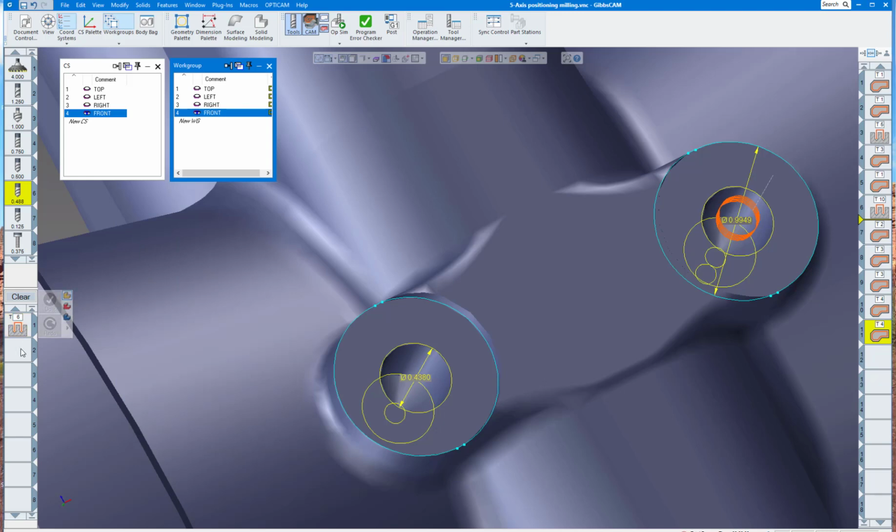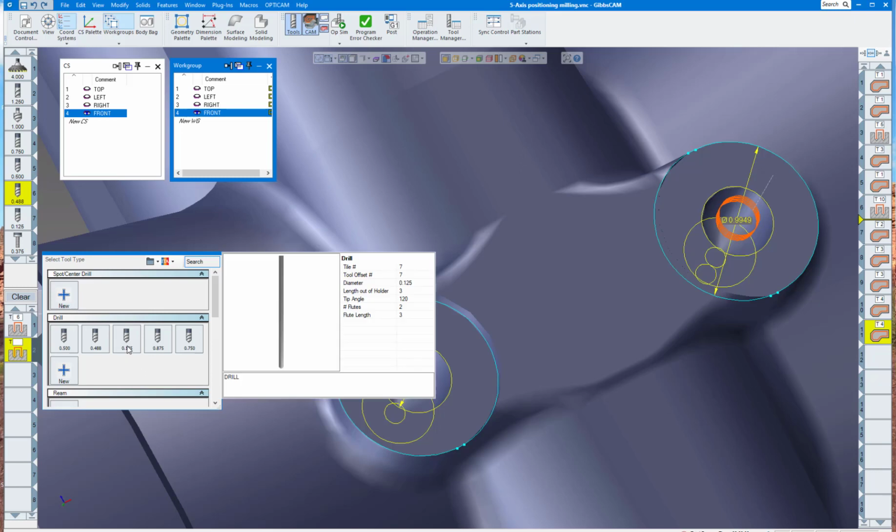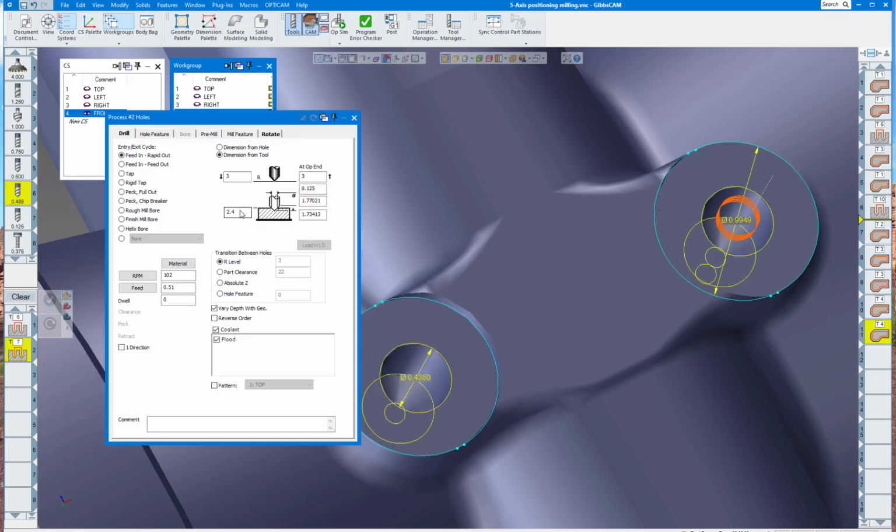Okay, so the next process is going to be another drill process. This is going to be the 1/8 inch drill. And I want to go down inside the hole a little bit closer, not start pecking way out here. So I'm going to highlight here. Alt click this edge here. That'll get me really close to 1 7/8. I can actually say this could be 2 inch if I want to get down a little bit closer. When I'm done, go to 3 inches there.